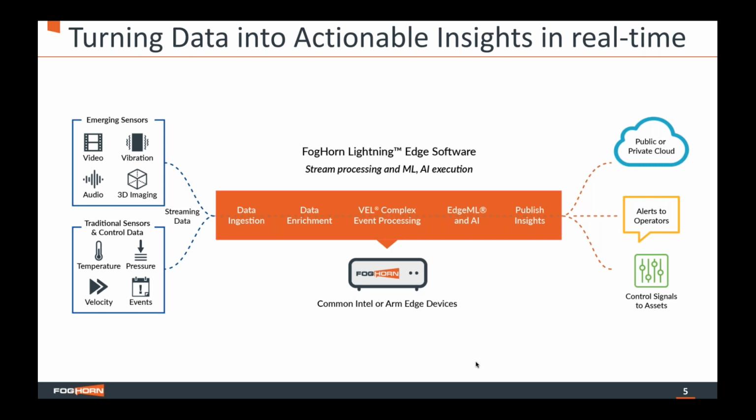And then we ingest it through this layer called the data ingestion layer. The data ingestion layer supports ingesting from many standard industrial protocols: OPC-UA, MQTT, Modbus, Zigbee, CAN bus, BACnet. Now we're doing Ethernet IP, a number of these different protocols that we're supporting based on the type of sensors and the devices. And then it goes through a series of processing layers in the data pipeline here.